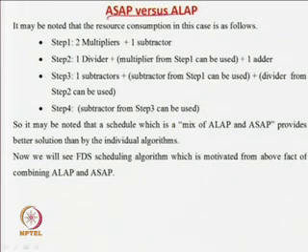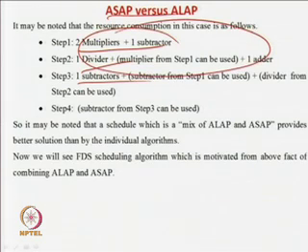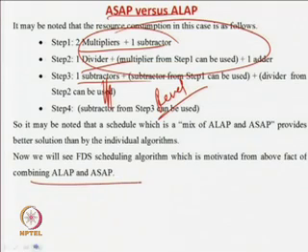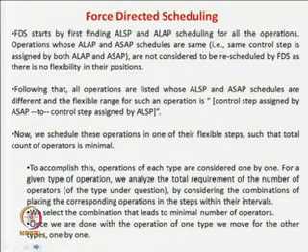So, finally, we achieved this one, which is the best solution: 1 adder, 1 subtractor, 2 multipliers and 1 subtractor. Okay. So, these are the resource requirements and these are actually all reused. Okay. So, that is what we have said. Now we will be combining as soon as possible and as late as possible. That algorithm is called force directed scheduling.